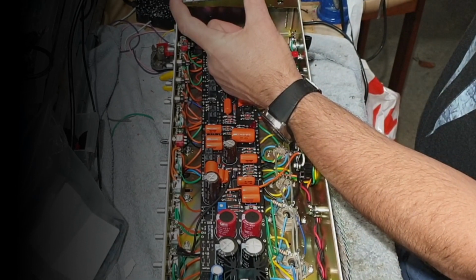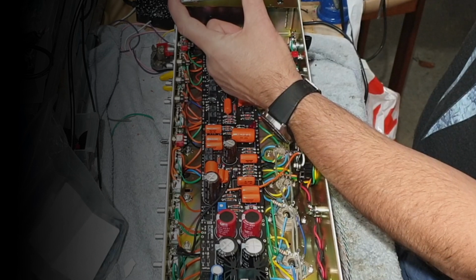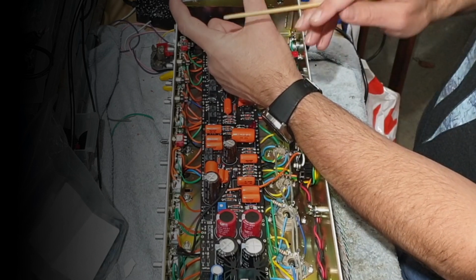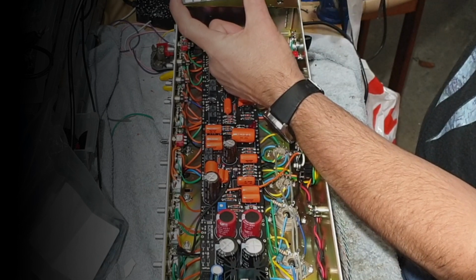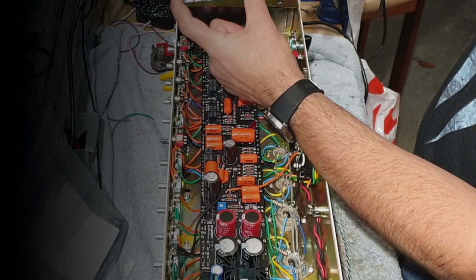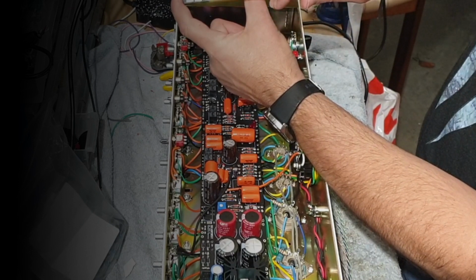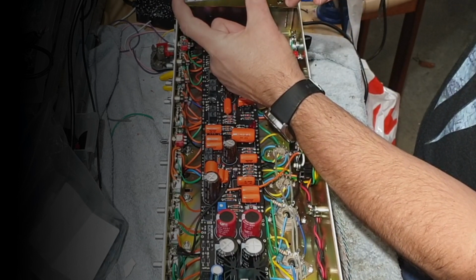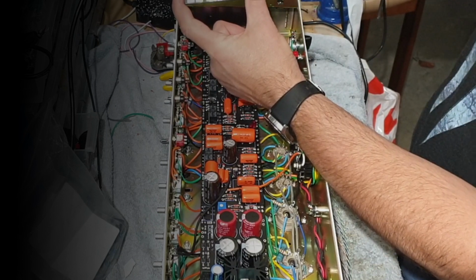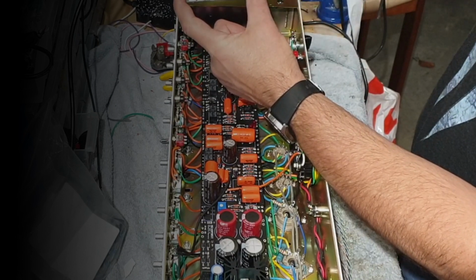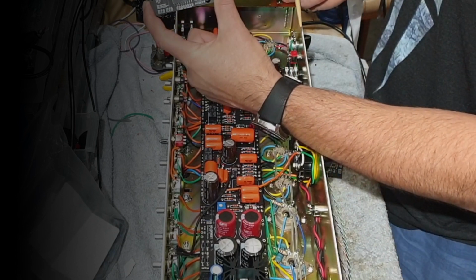You need to toggle a momentary ground on these inputs, and in turn the chip here will interpret that signal and set a latching state via this NPN array chip. On the bottom of the board, these are the outputs that will actually control the relays. So a pulse here will set these off or on. That's the way to think of it.